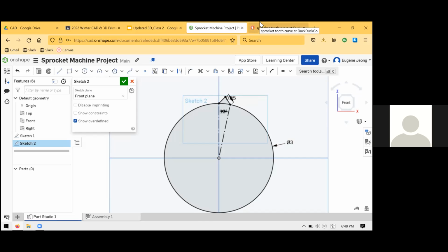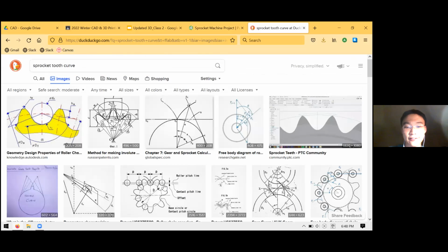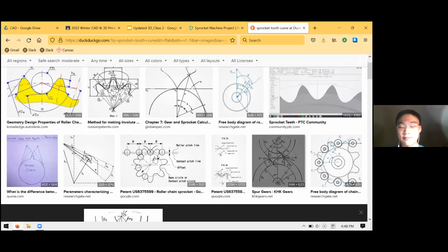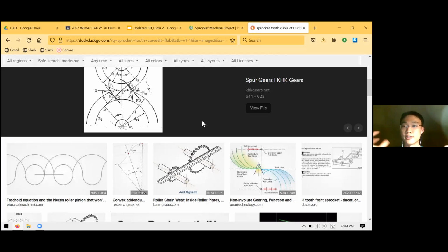As you work on this, as an aside, if you're actually interested in modeling realistic sprockets, there's a lot of interesting math involved. It seems from this cursory search that they have what's called an involute profile. An involute is a curve with an interesting property: if you have two meshing gears, or in this case a sprocket, with involute profiles, you get a constant velocity between the two gears.